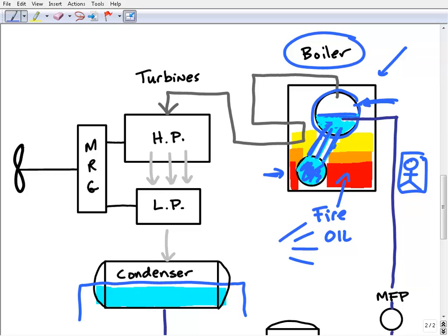All right, so this is where we're going to continue this process forward. So now that we got steam, I'll put it right here, steam, okay? This is very, very powerful steam at this stage of the game. And it's what we call saturated steam, or wet steam, okay? So the steam is coming out, and it's all dependent on your boiler types, but you could be coming out of the boiler at, let's say, maybe 700 psi. It could be a little bit off, but if my memory serves me correctly, this is pretty close to what it could be.